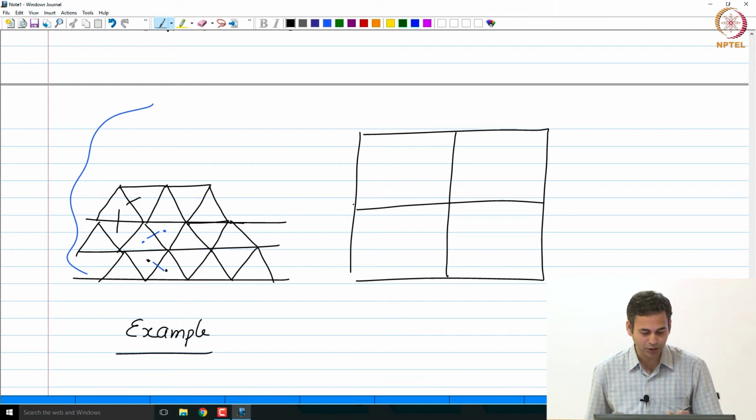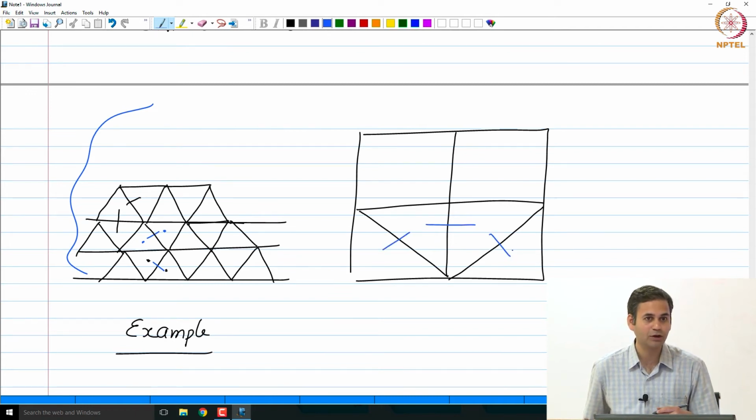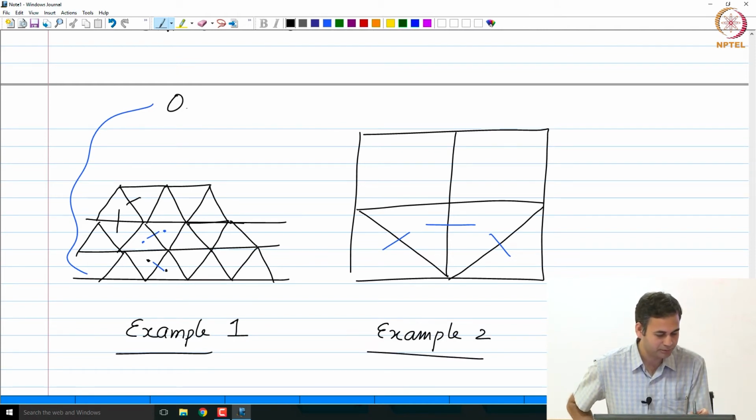Essentially I would draw this way, right, this would make the mesh here, and then which way shall I draw? Either way is fine. This way, right, would it make an orthogonal mesh? Essentially these all should be parallel to the cell centroid directions, okay, and so on, right. We can do this. So these are some examples of orthogonal unstructured meshes.